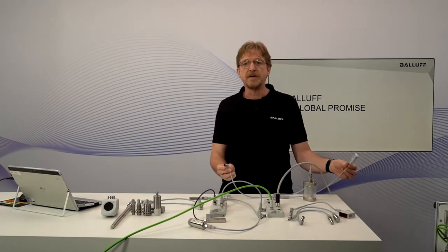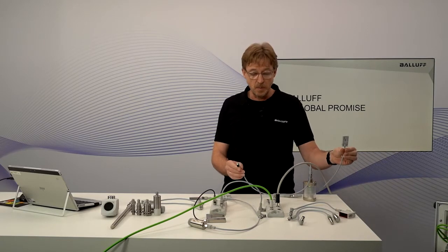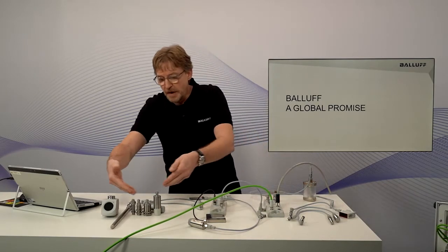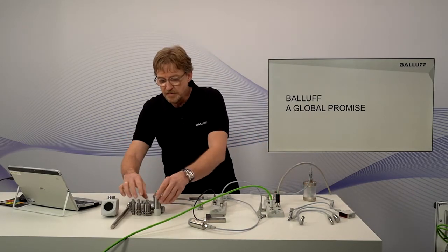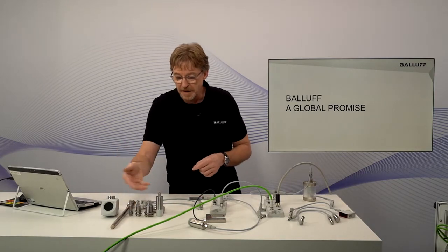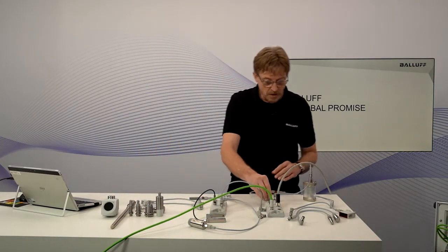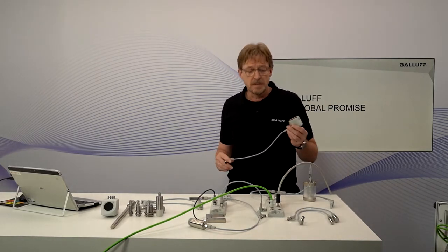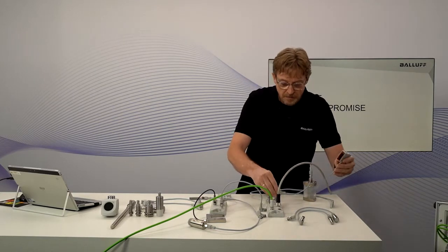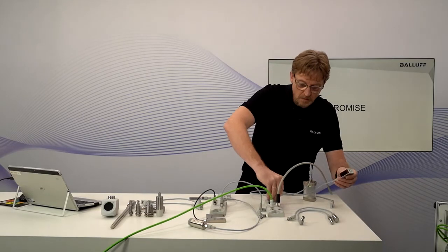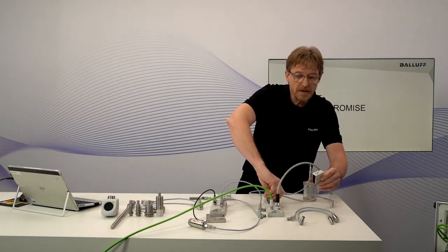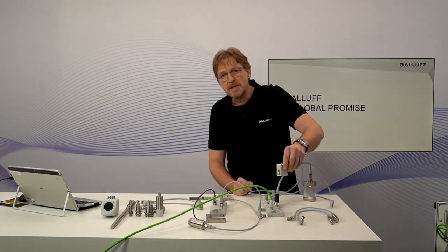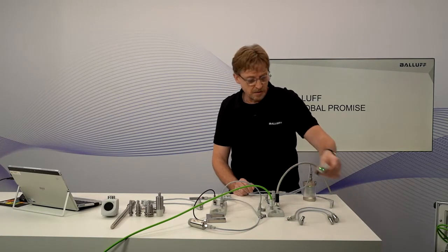And then we go on with an RFID read-write head, for example, which is this one. This is one type of our RFID read-write heads in that system. You see here a number of other RFID read-write heads in M30, M18, or M12, in HF or in UHF, different styles. We are using this. Next one is an optical sensor. This is a through beam sensor with red light. We will connect this to the next port. And as soon as it is connected, you will see that the power is provided from the port.